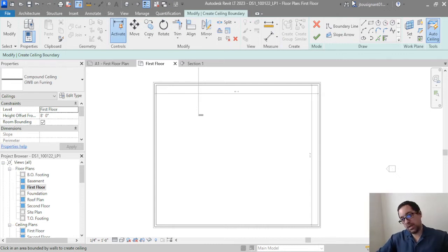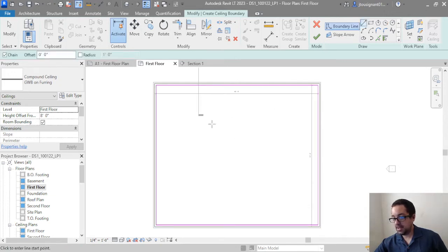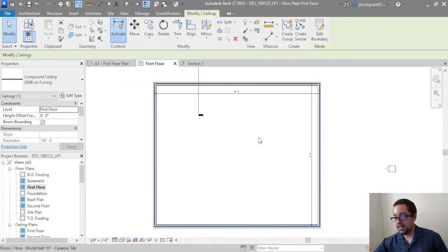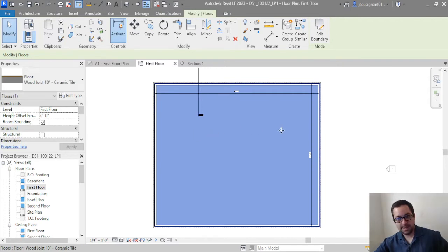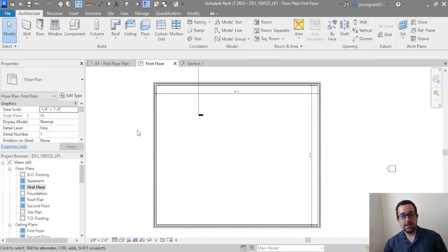So we're going to go ahead and try and place this automatic ceiling though, because our view range is allowing us to place an 8 foot. So I'm just going to place and click in this room. That's going to place the automatic ceiling boundary tool, and I can press check and it's going to have it placed. Now, when I click, I'm not going to click on the ceiling because I'm looking down, because Revit prefers you to be in a floor plane when you're building this ceiling.